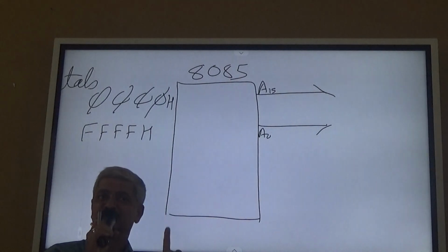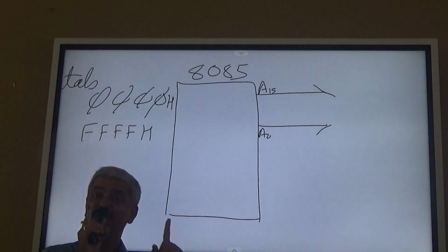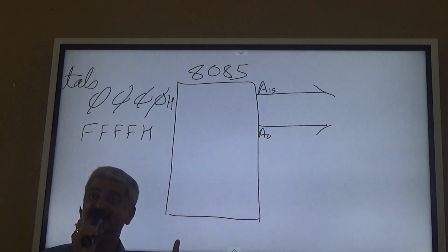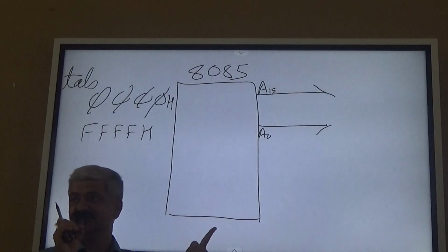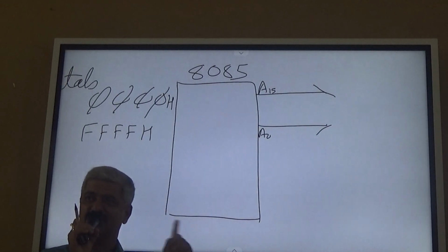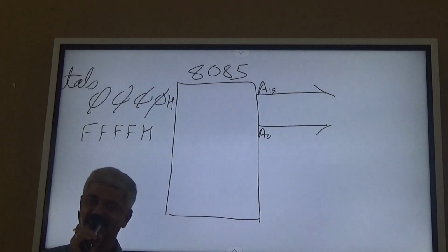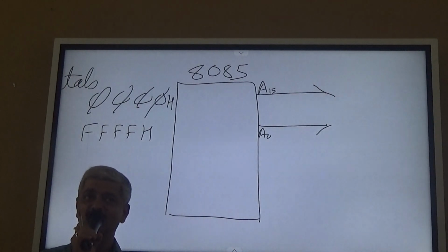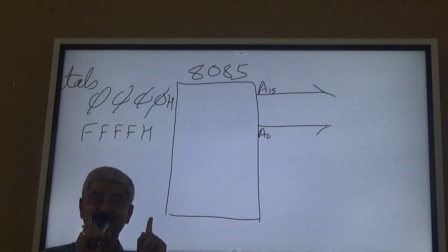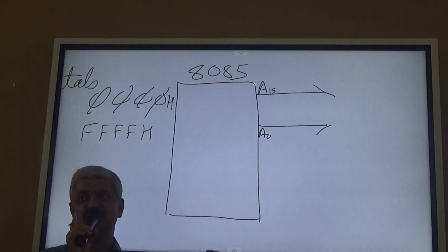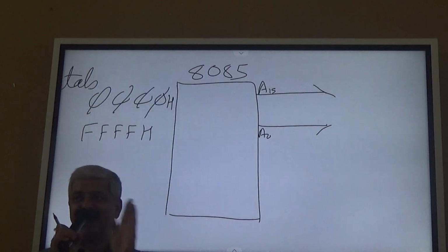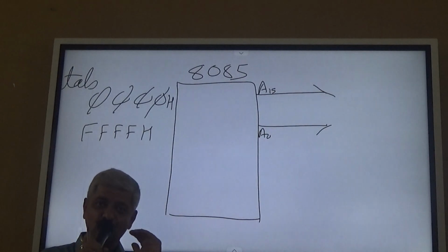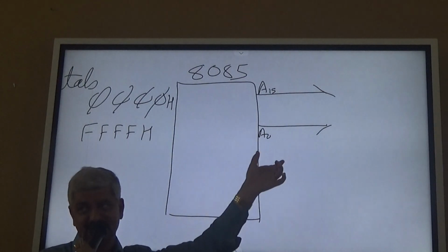So what are the possibilities which a microprocessor can do? There are 2 raised to 16 possibilities because there are 16 address lines. So 0000H to FFFFH, or in decimal, 0 to 65535. 2 raised to 10 is called 1K, a short form, kilobytes, because each representation is 1 byte.